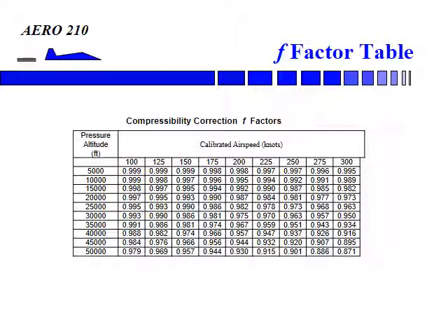But at high altitudes and high airspeeds, where the Mach number is much higher, we see that the correction is much more significant. The value of F is a lot smaller and the correction is not at all trivial. And that's why we call it a compressibility correction, because it's more significant when the flow is more compressible.